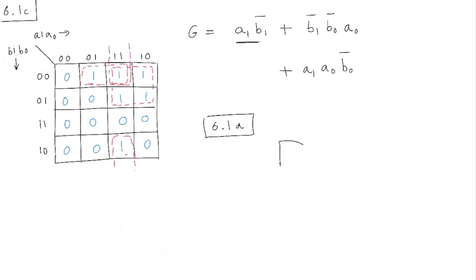So we have an AND gate here, and we can just give it the inputs A1 and B1 bar. Of course, you can show that B1 bar is generated from a NOT gate, but I think this is enough. Okay, and then we want to generate this, but this is a 3-input AND operation, so we'll have to make that 3-input AND gate using two input AND gates, right?